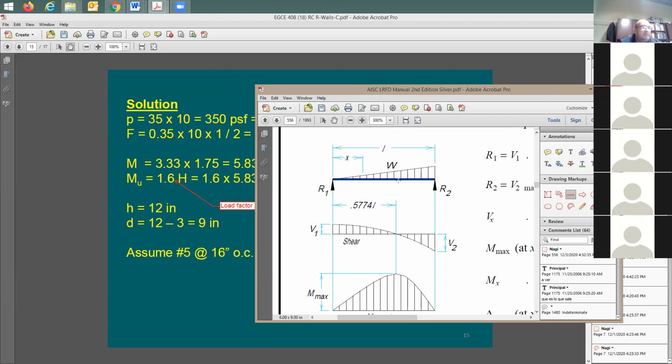Find out this amount of pressure right here and take the section right here at this place. You're going to have one force coming this way at 1/3 of this distance, and you have the reaction coming up. You're going to be taking the reaction times this distance, subtracting this force, which is equal to the integration of this triangular shape multiplied by 1/3 of this distance here.